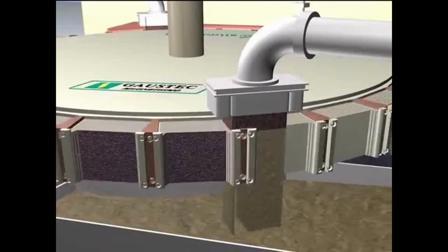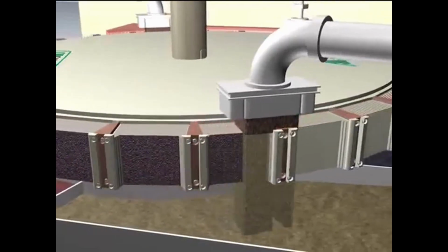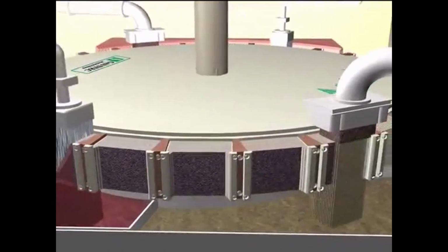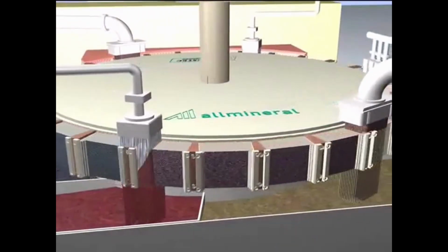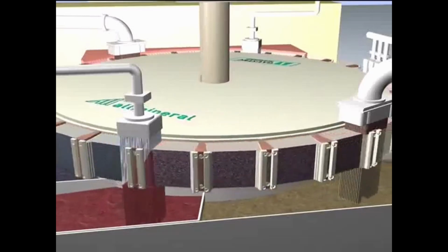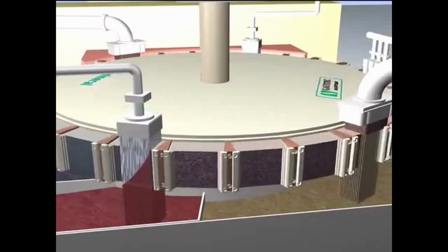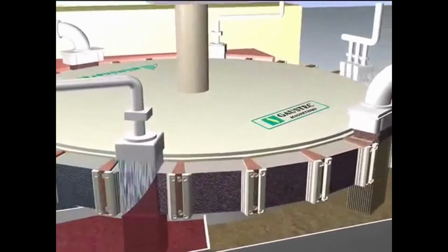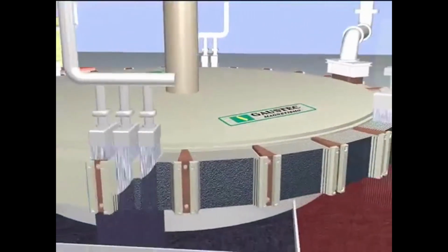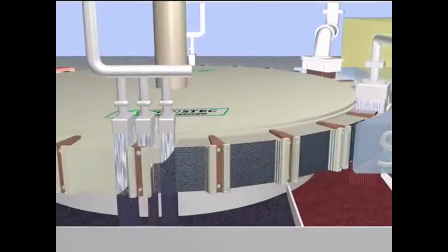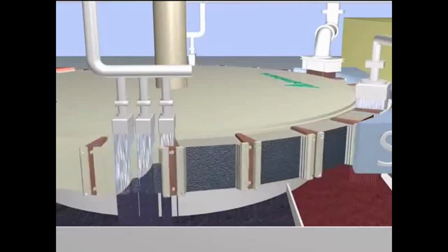Where can I use this machine? Iron ore, for example. If I feed this machine with iron ore, instantly I have tailings, then I have middlings, and these middlings are carrying iron ore, so iron particles. That's why I'm going to use flotation on this flow, okay? But the last flow, that's the magnetic concentrate, okay? That's ready to be marketed, and that's why I'm going to take this last material right over here and just sell it as a final concentrate, okay? So I'm really good to go with just this machine.